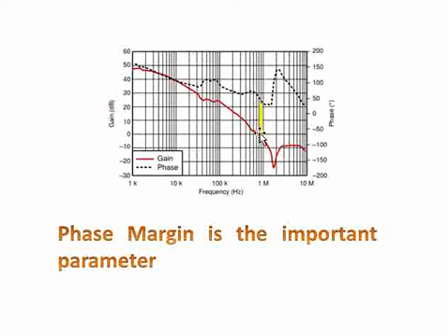Gain is zero means that beyond that it is all negative feedback. So when gain is zero, you can see here the difference to the phase margin. Gain zero is at around, for example, minus 60, and then till the phase it is zero. That means there is a phase difference of almost 50 degrees. So this is how we calculate the phase margin.